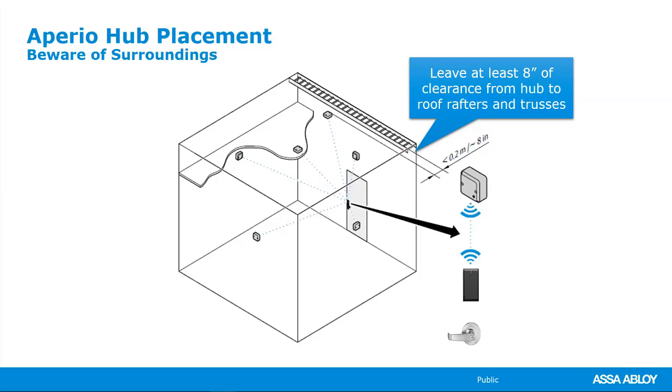Typically we see 50 feet is pretty standard through 2 normally constructed walls. So we will have variances. If it's an open line of sight, you may be able to gain a greater distance. But at the same time, which we're going to look at too, if it's an RF dense area, you might get a shorter distance. So more hubs might be required for that specific area. But really what the goal is to remember, there's nothing set in stone. It's whatever works specifically for your facility.